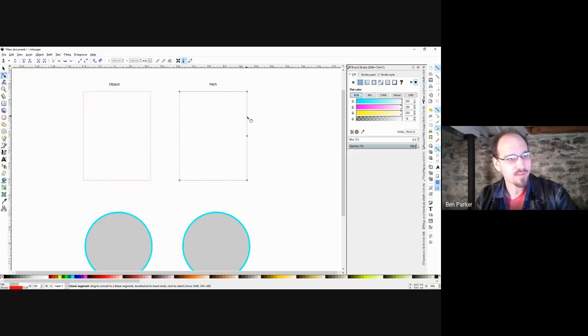Now you can take one of the segments between two nodes and drag it, giving a curvature of sorts, and select a node on one of those curves, on the endpoint of a curve, and you can change the handles to get different types of curves. And that's fun.